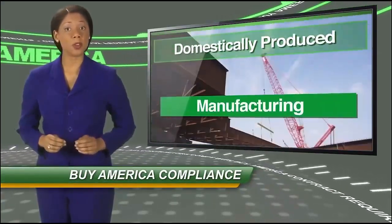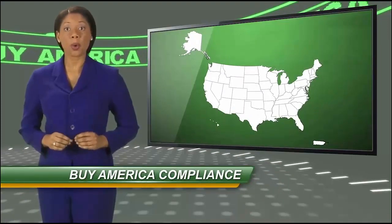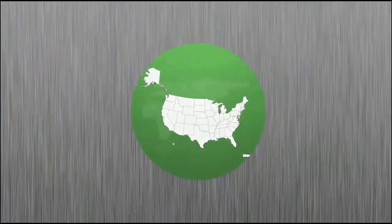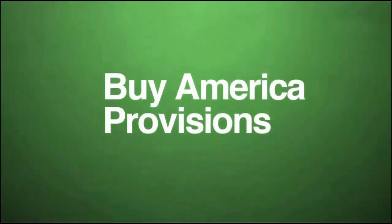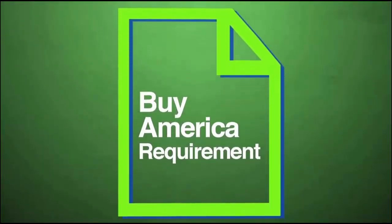Domestically produced means that the manufacturing, the fabrication of steel or iron products, and the application of coatings are performed within the United States or its territories. Products used temporarily during the construction are not subject to this requirement. Manufacturing or fabrication performed outside of the U.S. on a domestic iron or steel product makes the entire product a foreign source material that does not conform to the Buy America provisions. For example, 100 pieces of steel guardrail that are rolled to shape in Detroit and then hot dip galvanized in the Canadian city of Toronto does not constitute conformance with the Buy America requirements.